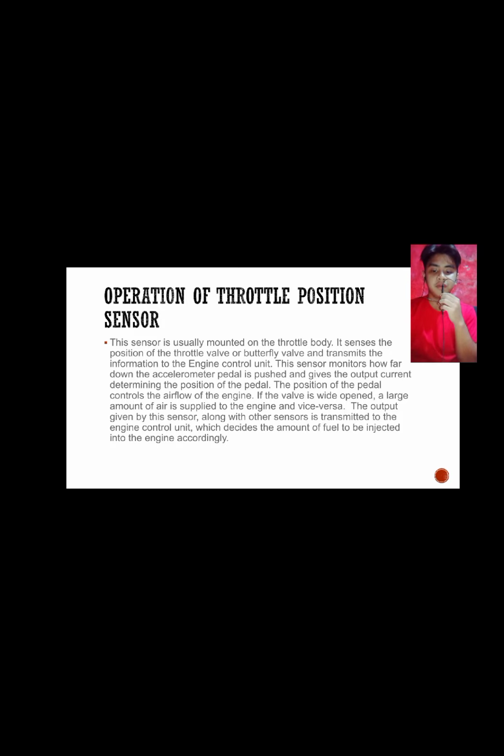The position of the pedal controls the airflow of the engine. If the valve is wide open, a large amount of air is supplied to the engine and vice versa. The output given by this sensor, along with other sensors, is transmitted to the engine control unit, which decides the amount of fuel to be injected into the engine accordingly.